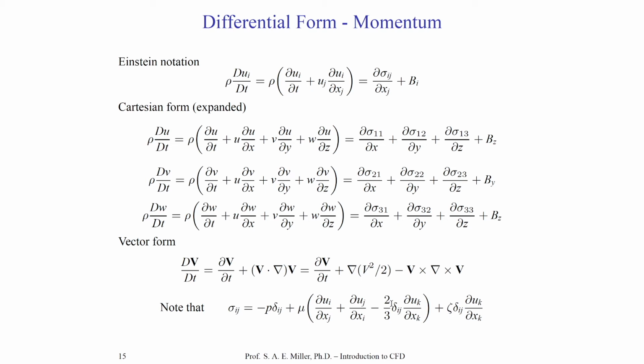This is quite wonderful, and for incompressible flows greatly simplifies the viscous terms that would need to be calculated. In fact, these types of terms might sometimes be called dilatation terms in the equations of motion themselves, because the fluid parcels are growing in volume and shrinking in volume. It's not so much to do with density, it has to do with the dilatation of the parcel.